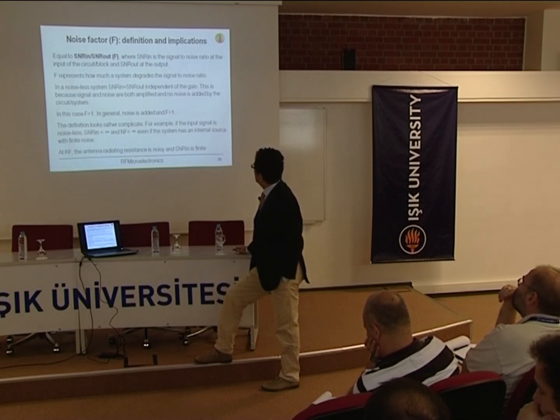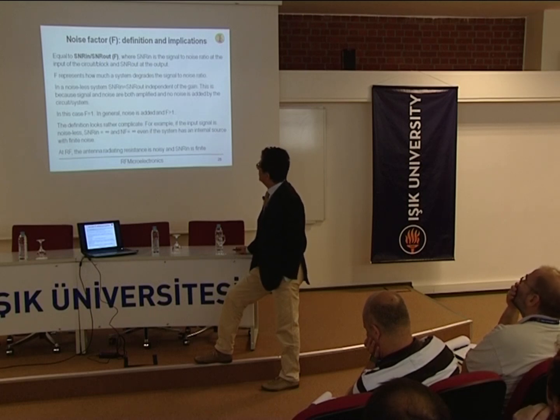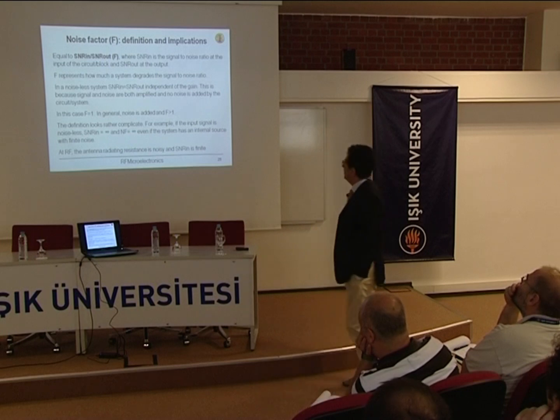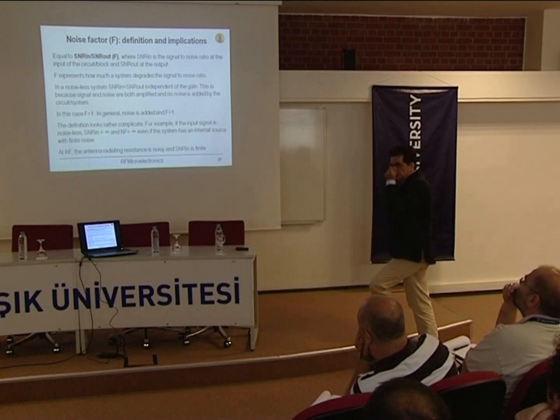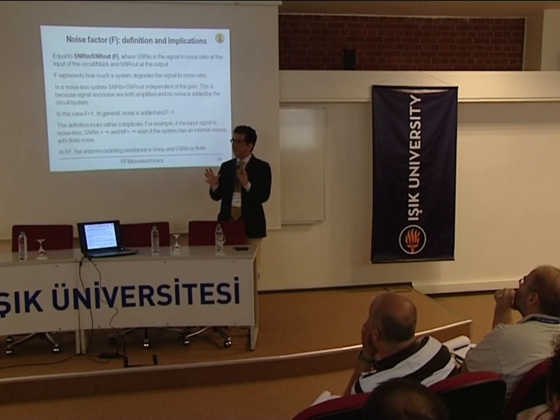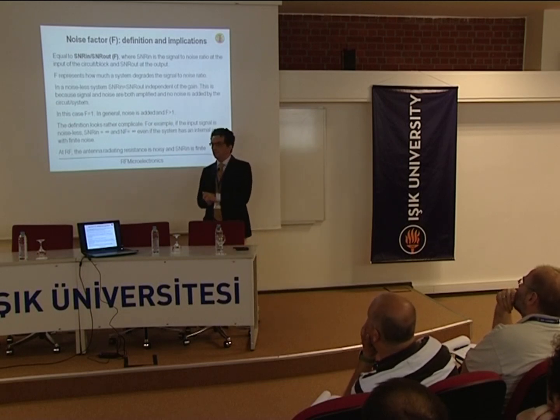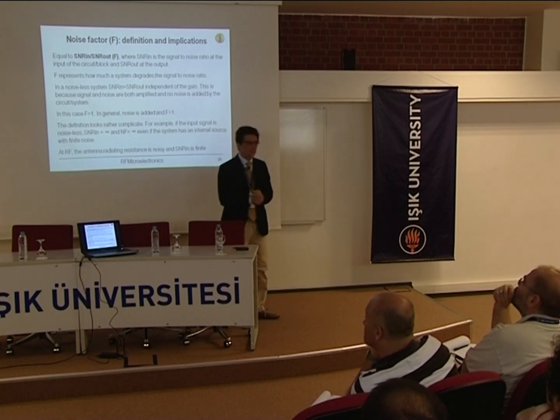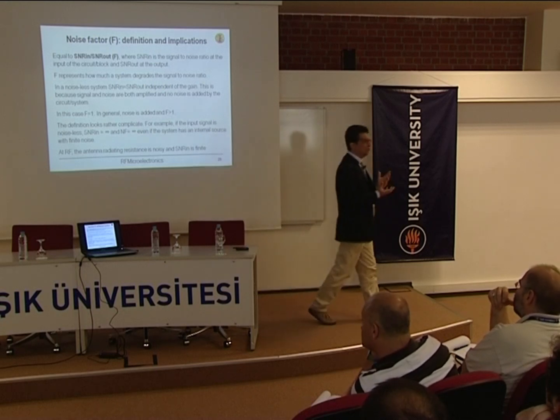Which means that F, the noise factor, represents how much a system degrades the signal-to-noise ratio. Or looked at in another way, we have a signal at the input that has some signal-to-noise ratio. So the signal is accompanied by some noise, and we have a relative difference in power between the two quantities.